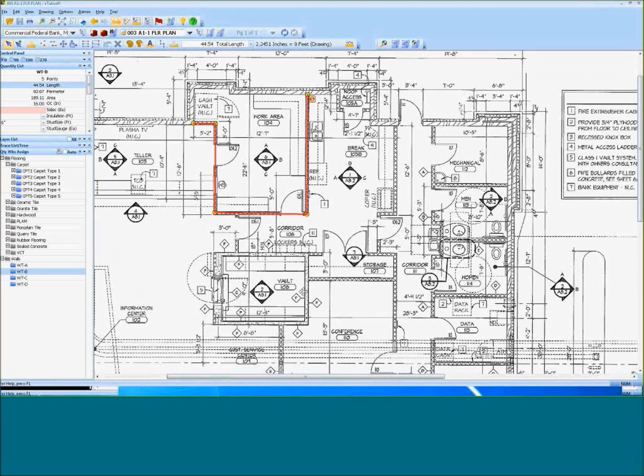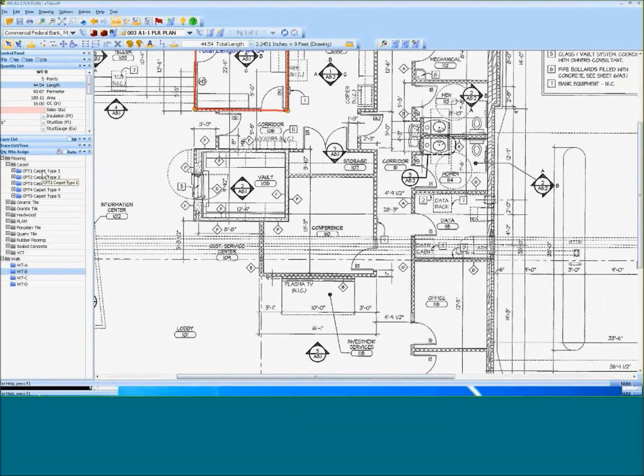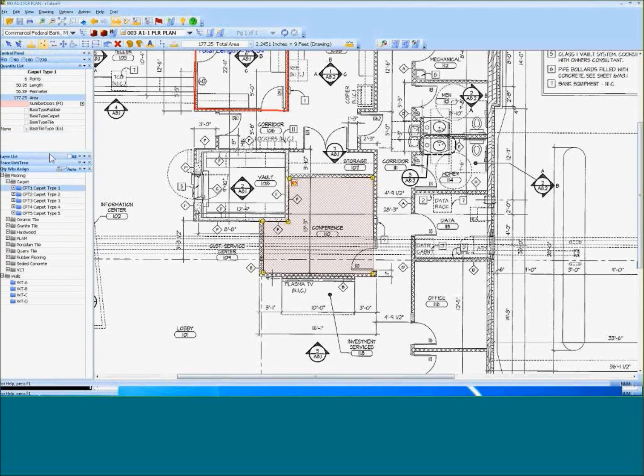Now, I could do something else. Let's say I want to measure some carpet. And I have a simple extension here, allowing me to measure the square footage of the carpet and get my color on the carpet. And over here in my extension I can enter how many doors, so I can take the perimeter of that measurement, subtract one door, and then it'll tell me I have rubber base and how much my rubber base is. So that's another simple kind of extension. Very nice, very easy to use.